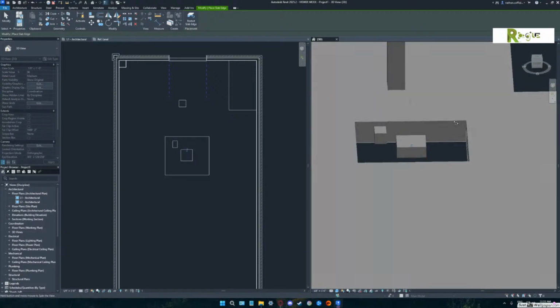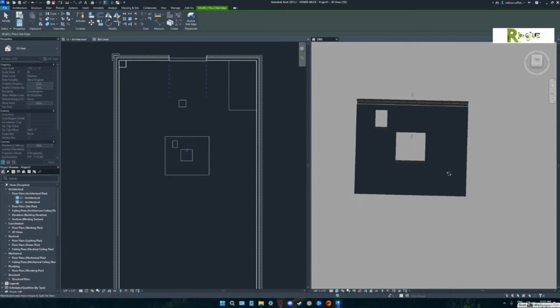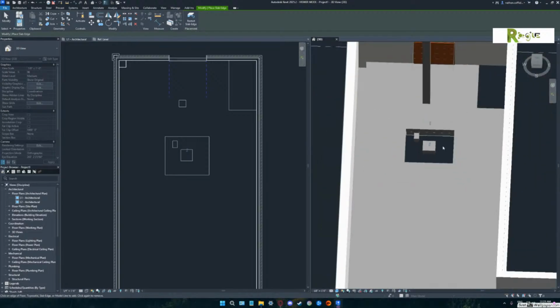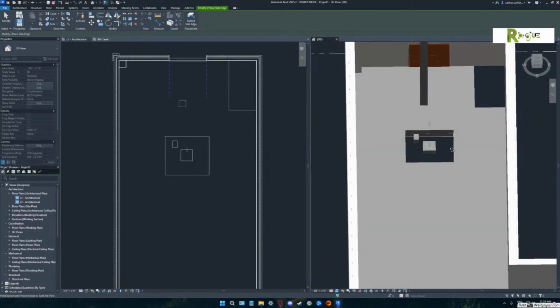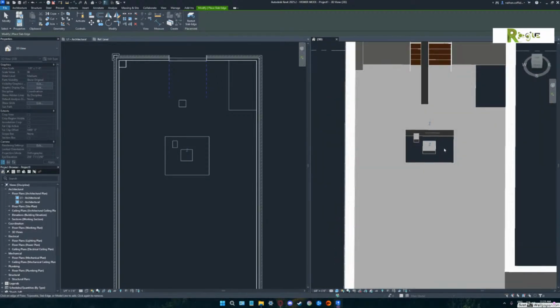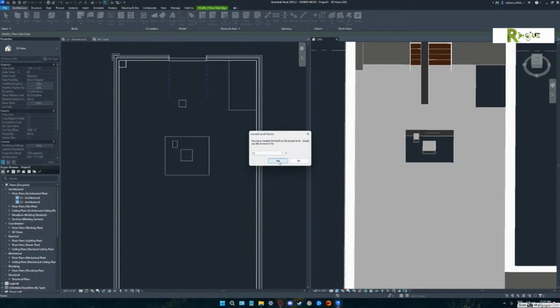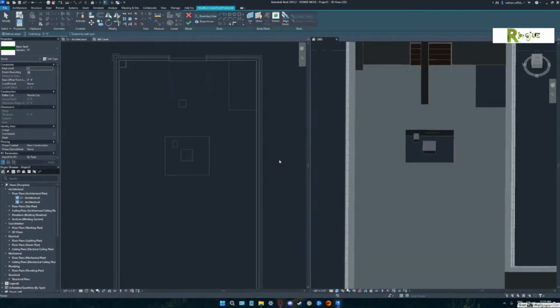But let's continue on with the floor, just like you did the floor. You should be able to do the roof. I was hoping that you would realize Eric showed you how to hover over the wall and hit tab to select all the walls. You can do the exact same thing with the roof. That's asking you what level you wanted to put it at. I think you did correct by saying L2 if that's your highest level. Right. And you're on your boundary line.